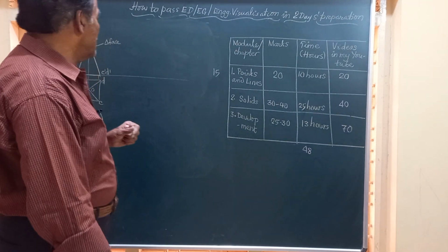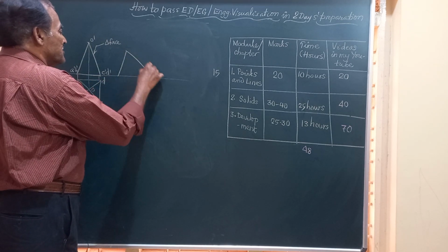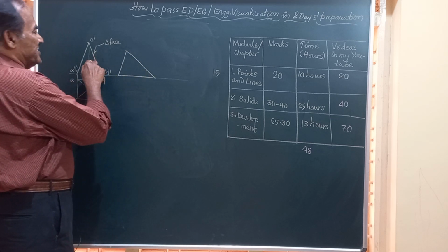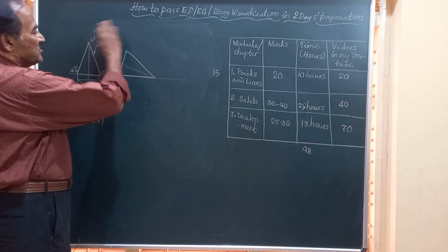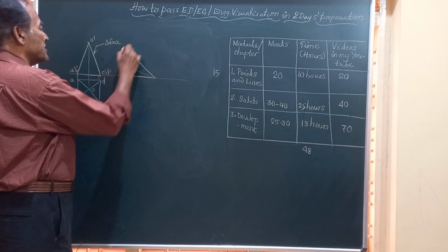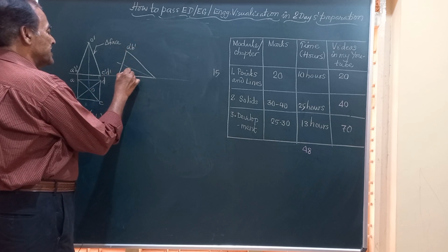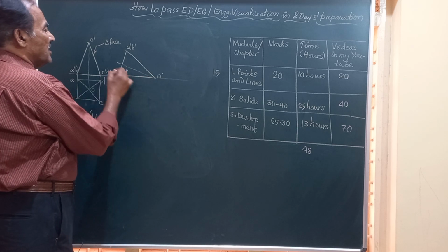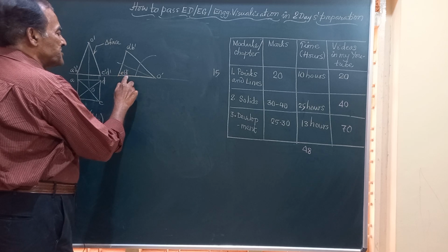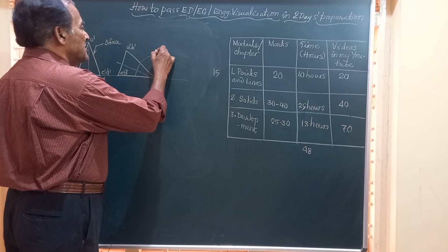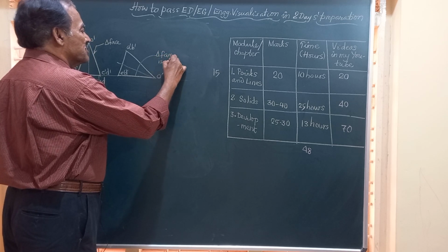In the next position, suppose they say it is resting on a triangular face on HP. So whatever figure you have here, friends, you redraw or reproduce it such that it is rotated here, and this line represents the base A dash, B dash. This is C dash, D dash, O dash. And friends, now the object is resting on O dash, C dash, D dash. There are 3 points on this line. Hence, this triangular face is on HP.